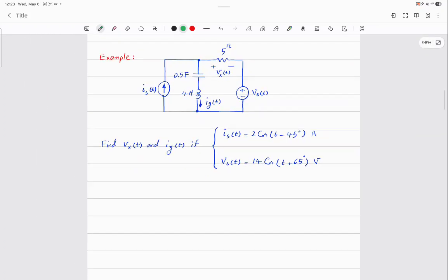Now, this is my question. Since we are in a steady state, can I just replace the inductor with a short circuit and the capacitor with an open circuit? Yes. Because it's steady, so you're not fluctuating. What was wrong with his statement? He said they are steady because nothing is fluctuating. Steady state doesn't mean it's still time.